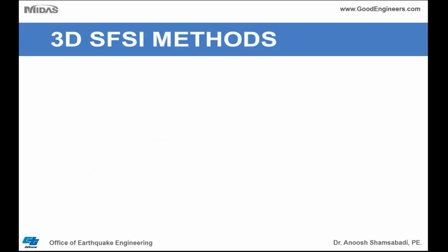Okay, so far we talked about how the boundary condition of the model is extremely important. Therefore, you need to be able to develop the correct boundary condition for the abutments and for the pile foundation. The boundary condition of the abutment, I showed you how it's developed, a very simple equation based on experimental data. And for the pile springs, I use Reese sand to develop the nonlinear pile springs.